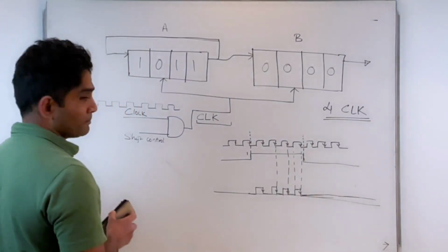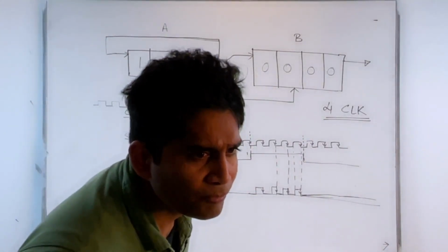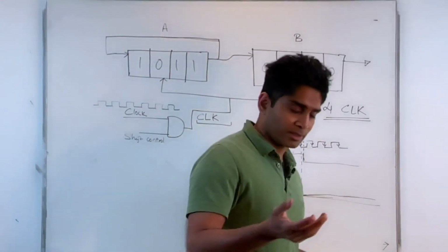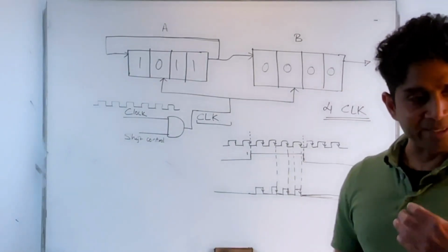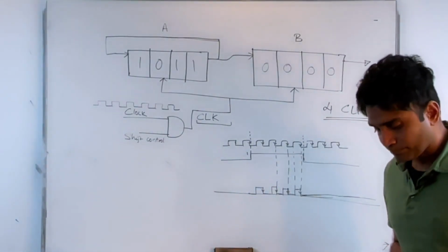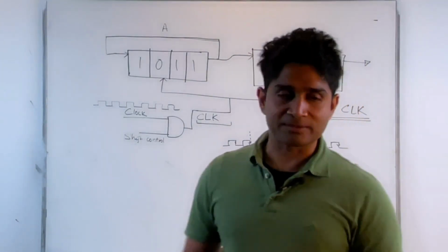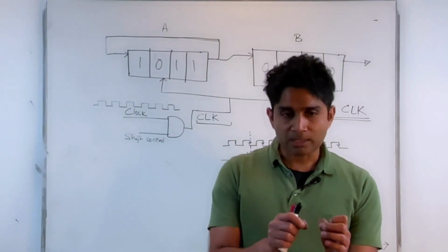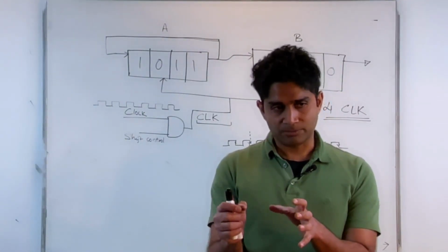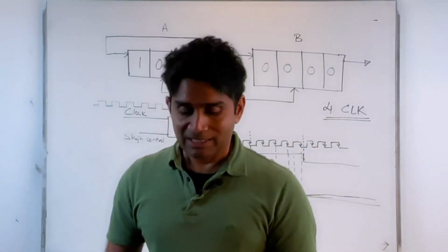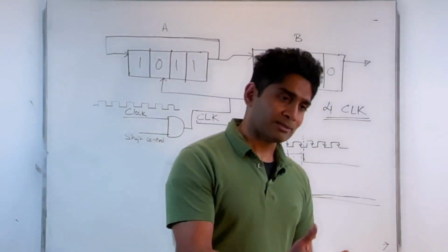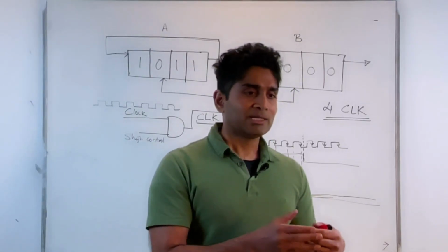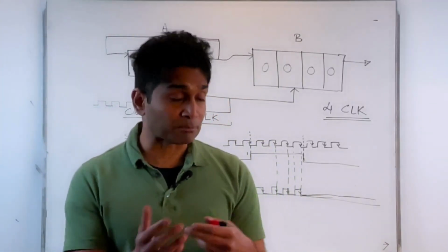Now let's go back. When you design the flip-flops, the question was, are we using only the negative edges or both negative and positive edges? Okay, let me correct myself. When you're designing a flip-flop, you design it either as a flip-flop that gets triggered on the negative edges, or a flip-flop that gets triggered on the positive edges, not both.